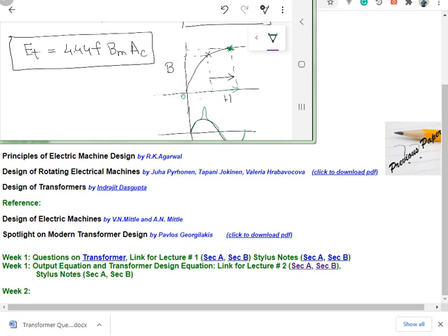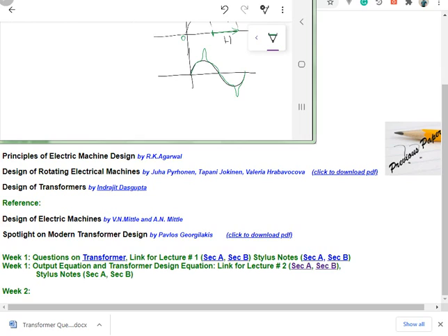From this 0 point up till this point, this is almost linear. But after this point, from here to here, this is not linear. For a very large increase in I, you are getting a very small increase in B. So there is a big bulge; practically I have drawn the bulge here, it may not be this big, but I've drawn it a little bigger so that it's visible to you. But it is having a high third harmonic component.